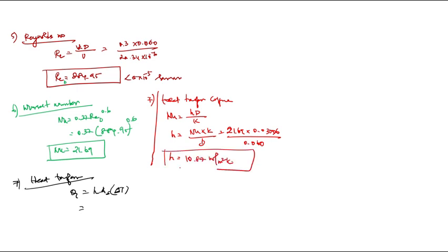After finding the heat transfer coefficient, we move to the next step, the eighth step, which is the heat transfer. So h is equal to 10.87. Here the surface area is an important factor; this is a sphere, so the surface area of the sphere is 4 pi r square, into delta T, which is wall temperature minus ambient temperature, T_A or T infinity.